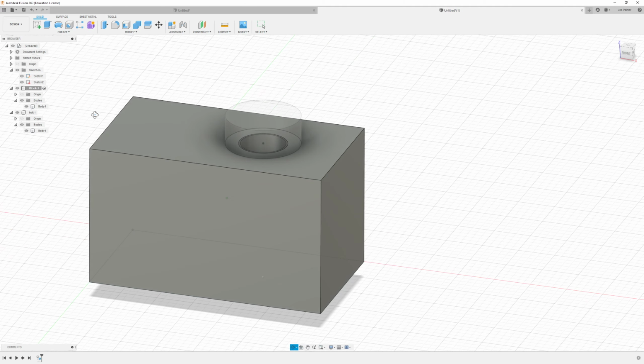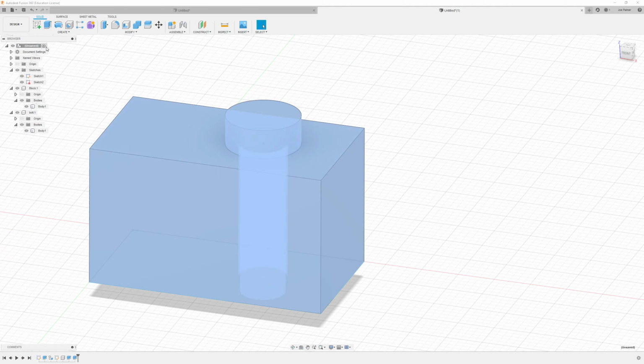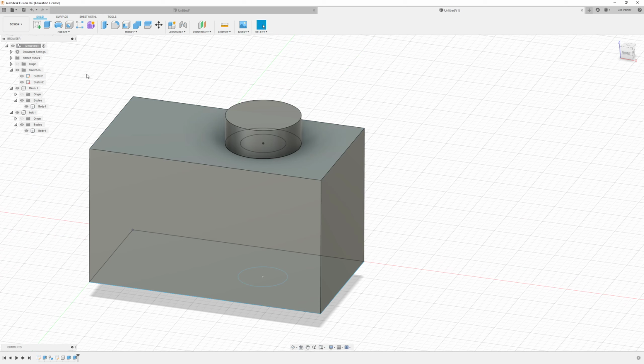So we need to be aware of this when we're making assemblies in this way. At present, there is no way to make sure that these sketches are actually within the feature tree for that particular component. So we need to create that sketch, and then the very first opportunity we get, we need to create our new components. Otherwise, we end up dividing features between the top level assembly and their respective components.